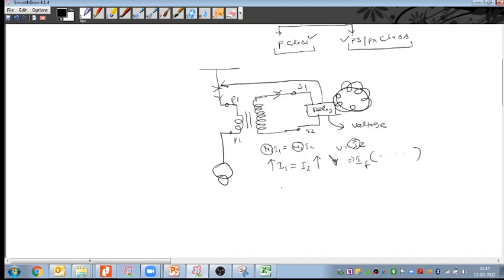Sorry to interrupt you, Raga. The voltage across S1 and S2, considering all the cable resistances and cable impedances, should not exceed, say, 400, whatever the knee point voltage is. Whatever comes, say 400 or 500, by the relay formula, that should be the value across it.